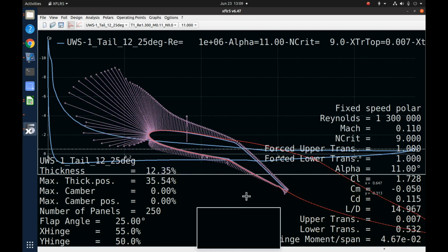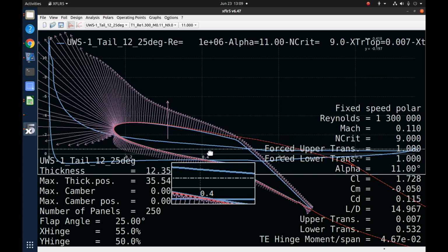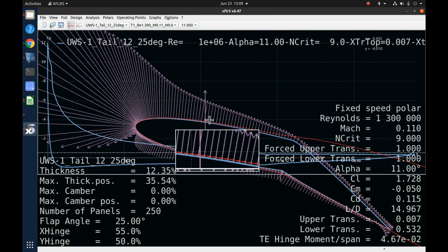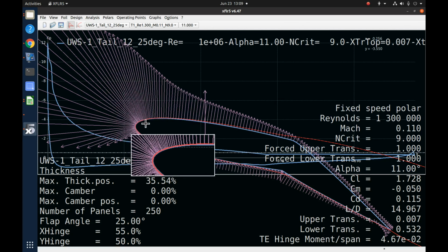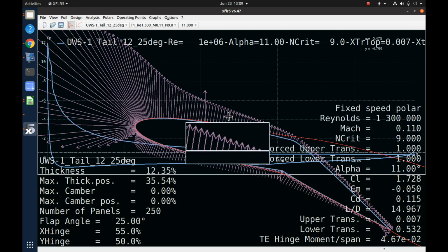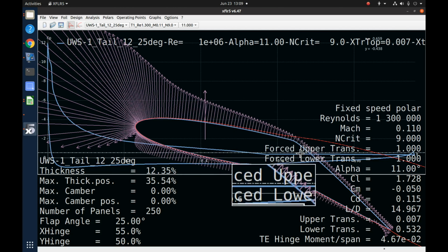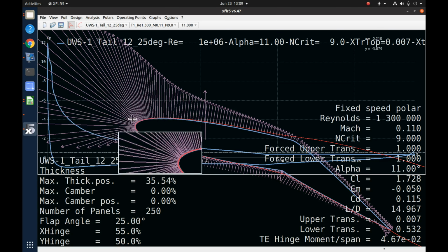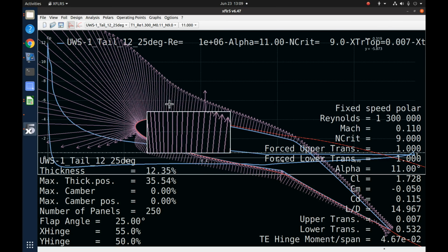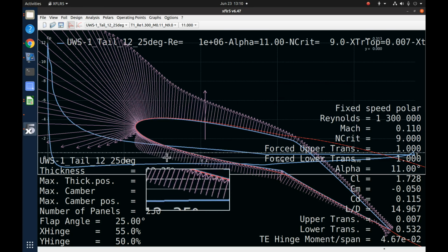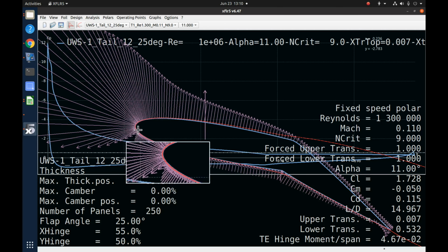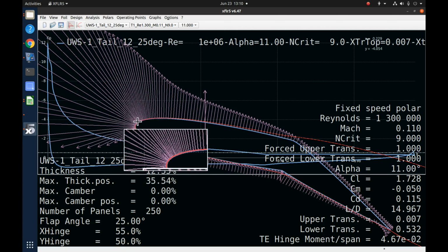But let's come back up to this big old purple dude here. So these purple lines are showing you the coefficients of pressure. And the direction is normal to the surface, or you can say perpendicular to the tangent at a surface. So this is showing you how the pressure is acting, the direction it's acting. You can see there's a lot of suction up here at the nose. A tremendous amount of the pressure is being pulled. These arrowheads show the direction. So in this case, it's suction. It's pulling away from the surface. Here on the bottom, you can see the arrowheads are pointing into it, so it's pressure pushing into the surface. So you can see this nose up in here is really trying to be sucked away.